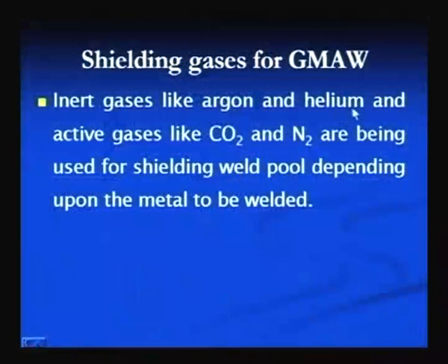The inert gases like argon, helium, or active gases like CO2 and nitrogen are commonly used for protecting the weld pool as per the kind of metal to be welded.